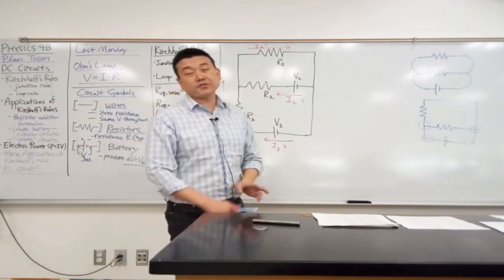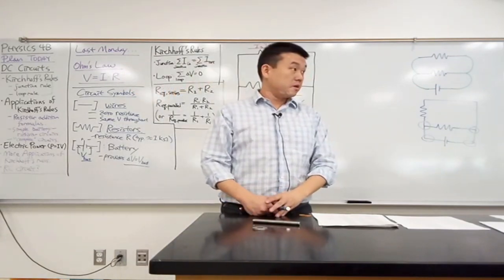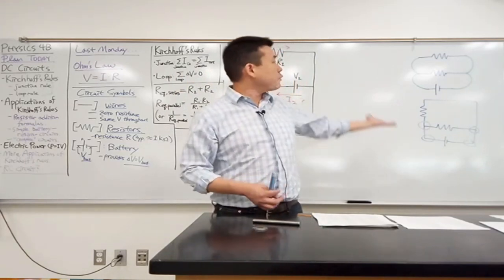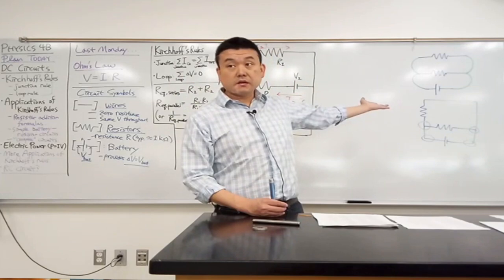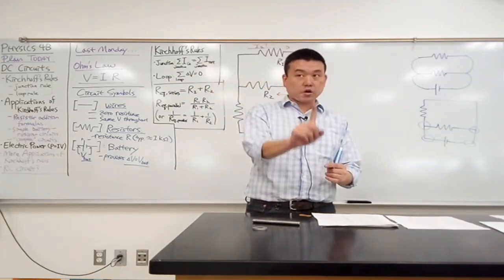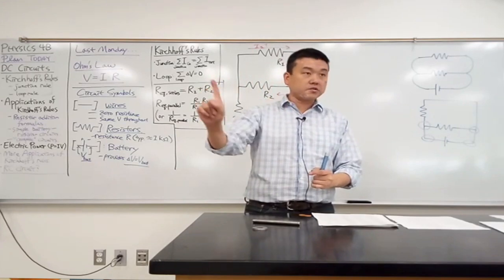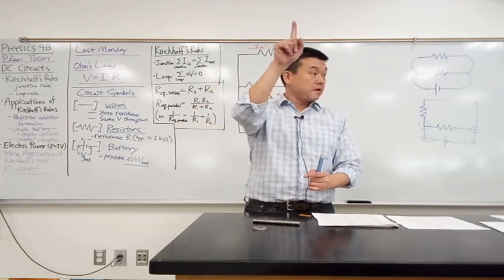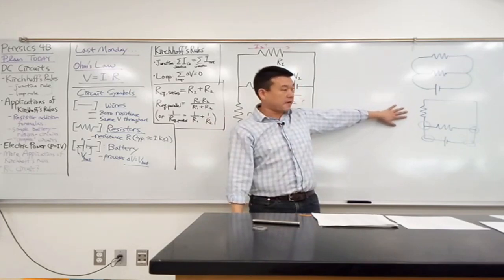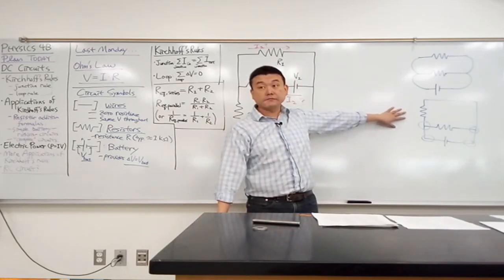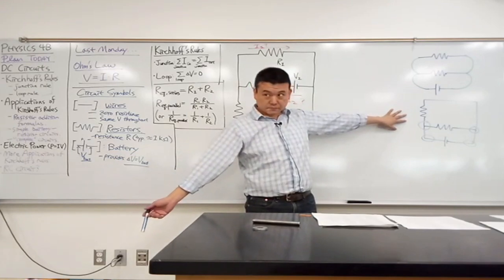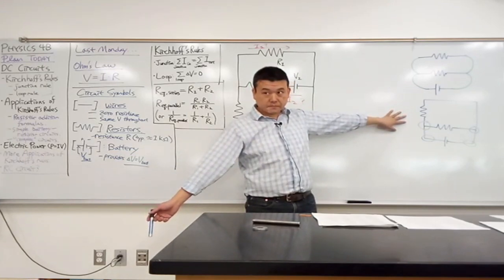So with the parallel, actually, I want you to pay attention to the voltage. Because it comes down to this. When we look at current, there's just way too many possibilities. So with the series, remember, we nailed down one thing, that when you look at the current, one same current passes through all the elements. I want to have something similar here, and if I try to do it in terms of current, I have no chance of doing that ever. So what other thing remains? Voltage stays the same throughout its travel through the circuit.